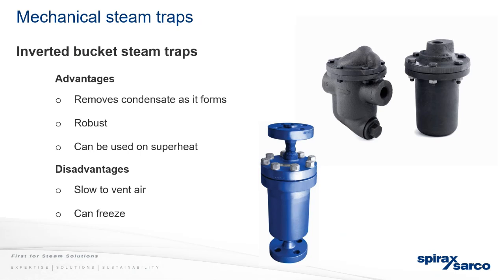I don't know if you want to add anything there, Cornelius, as well. Yeah, just potentially the other thing, you'll notice one of those at the top has a strainer built in, so dirt also has a potential to go and sit on the seat, and then the trap doesn't close properly when it's supposed to.